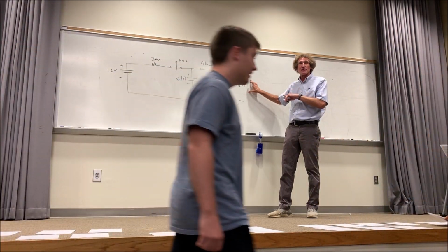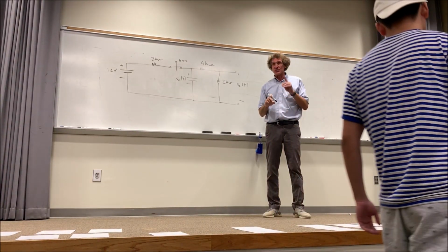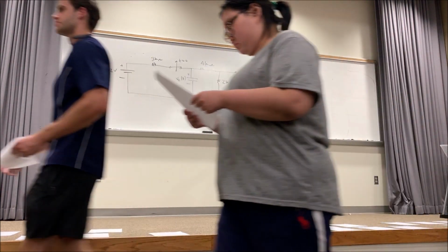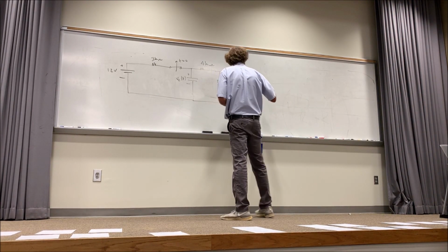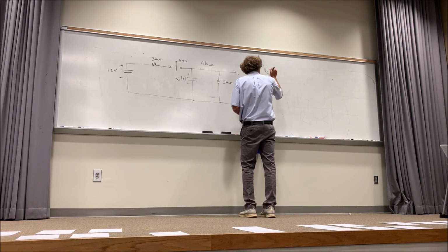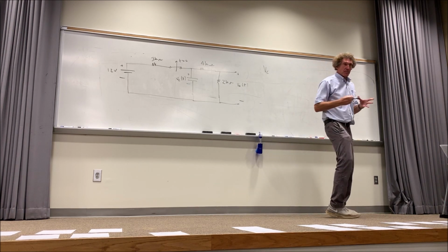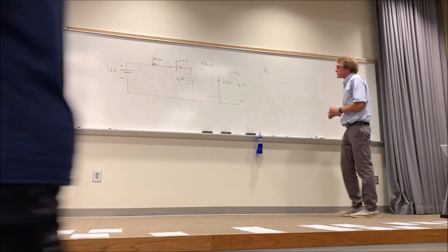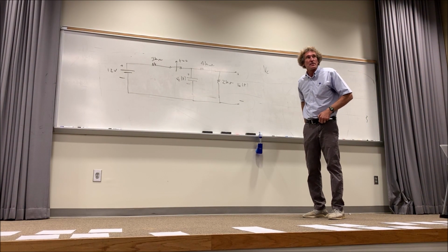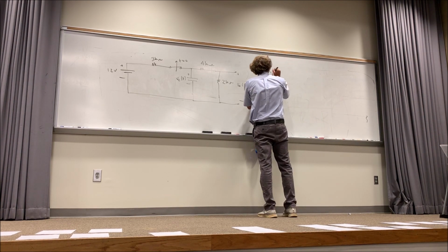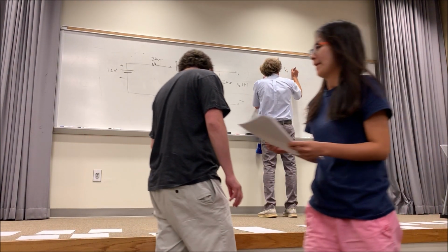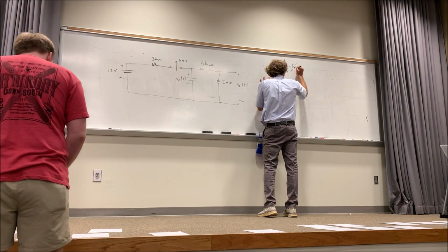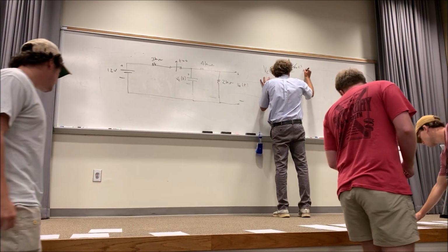But you don't get that voltage. You get the voltage across the capacitor first. You follow me on what I'm saying? You can get that voltage in a second after you get this voltage. So, the voltage across the capacitor, the general form is this. VC of t is equal to some k1 e to the minus t over R Thevenin times C, plus k2.